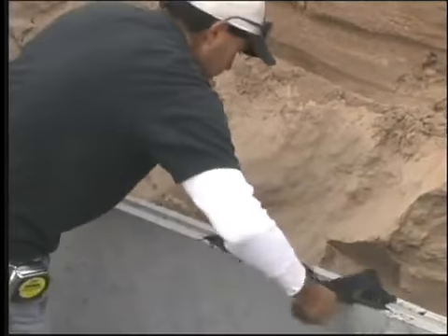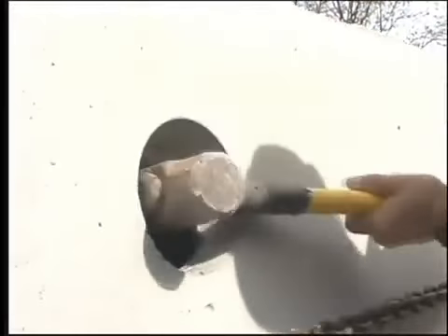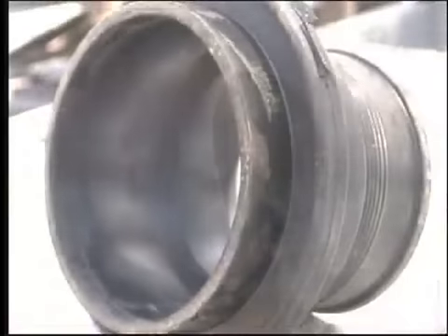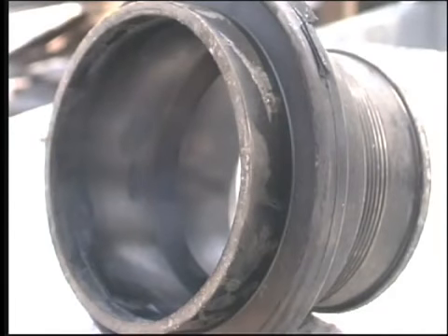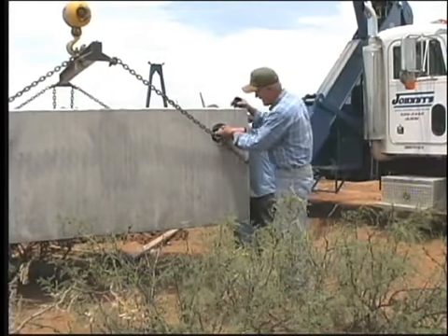and tree root intrusions. Your septic tank may have either a large diameter hole or a neoprene collar as an inlet to the tank. If the tank has a neoprene collar, the collar will seal the inlet and outlet holes. Wet the collar to allow the pipe to slide in. Do this with water, dish soap, WD-40, or hairspray.